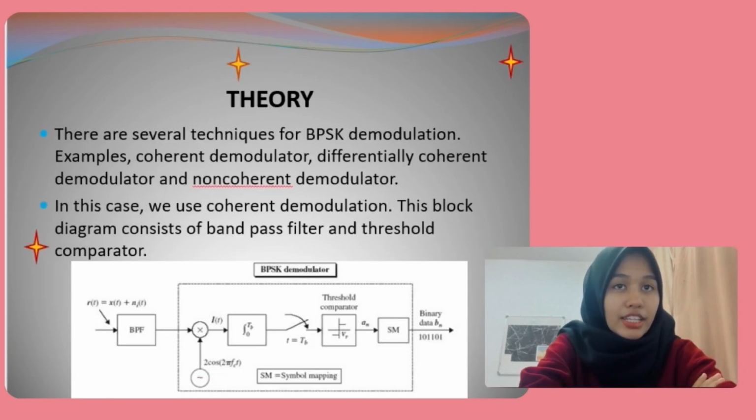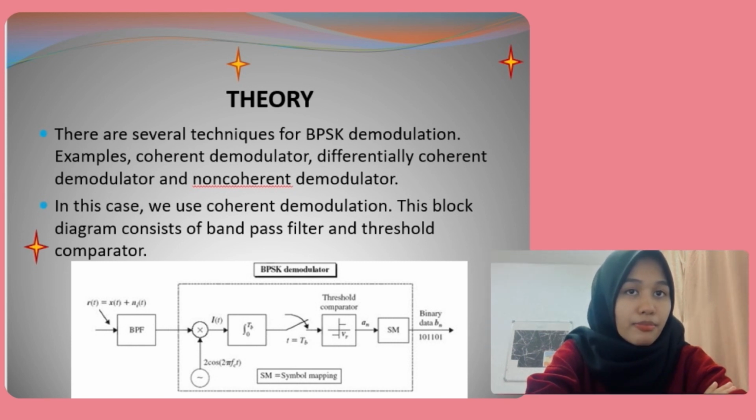There are several techniques of BPSK demodulation, for example coherent demodulator, differentially coherent demodulator, and non-coherent demodulator. In this case, we use coherent demodulation. This block diagram consists of a band pass filter and a threshold comparator. So this is our block diagram for coherent demodulation.